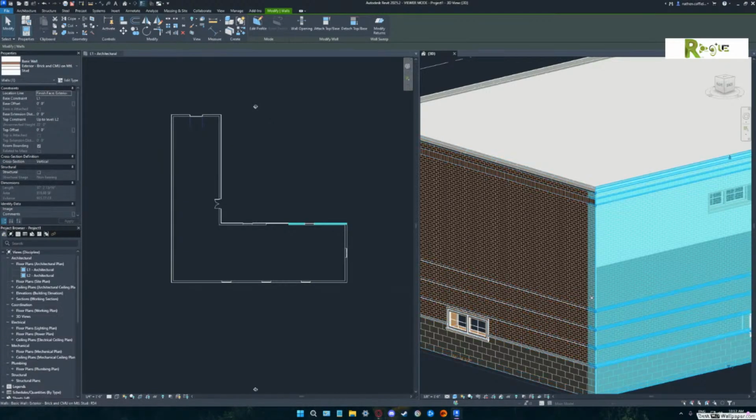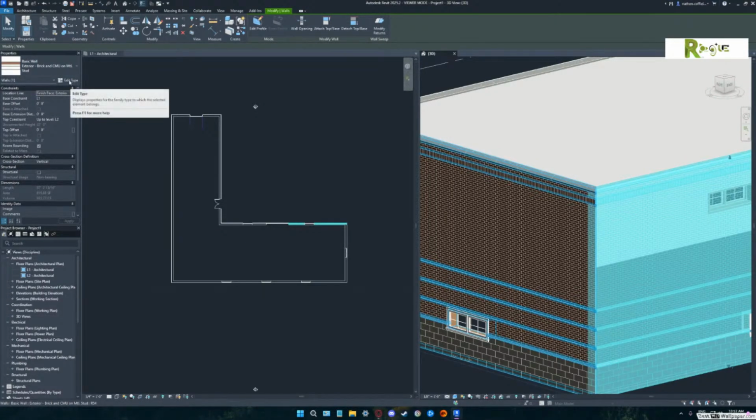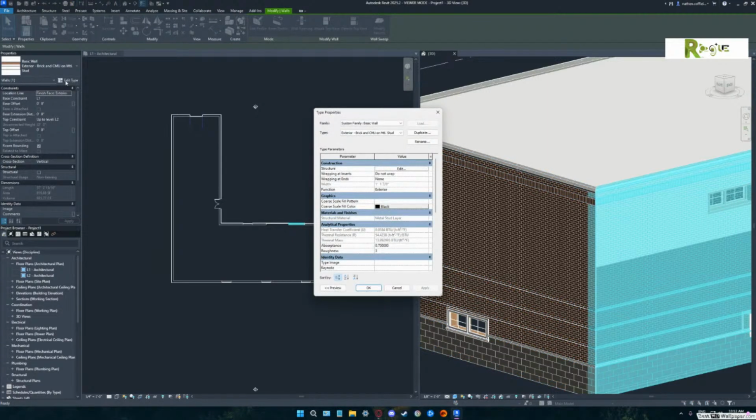So if we went over to the properties, right? Okay. That was where we picked our wall type. You see right below that it says edit type. Hit that. Okay. So this is an important thing. The twin brother of this will happen for our floor and for our roof. In other words, we're going to be able to edit the type, but all of these are called system families, and they have a little bit similar flavor to them. But the big thing that we do when we want to edit a wall is the very top button is the structure, and you can hit edit on that.